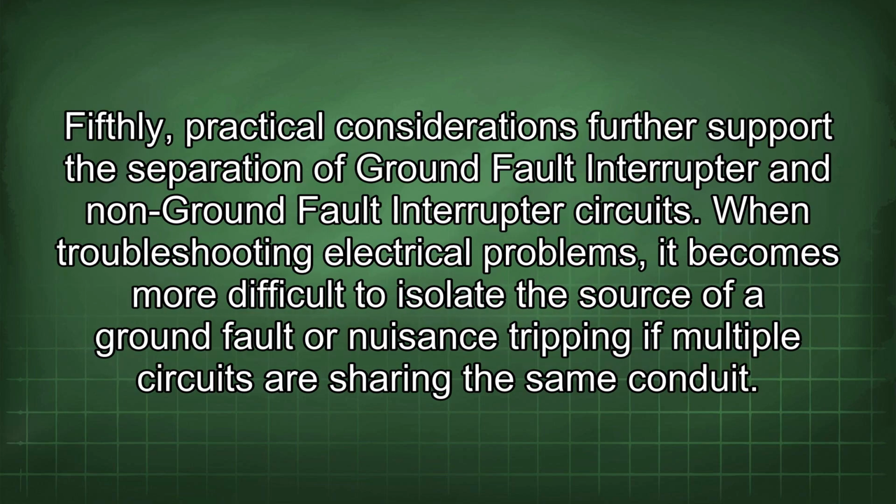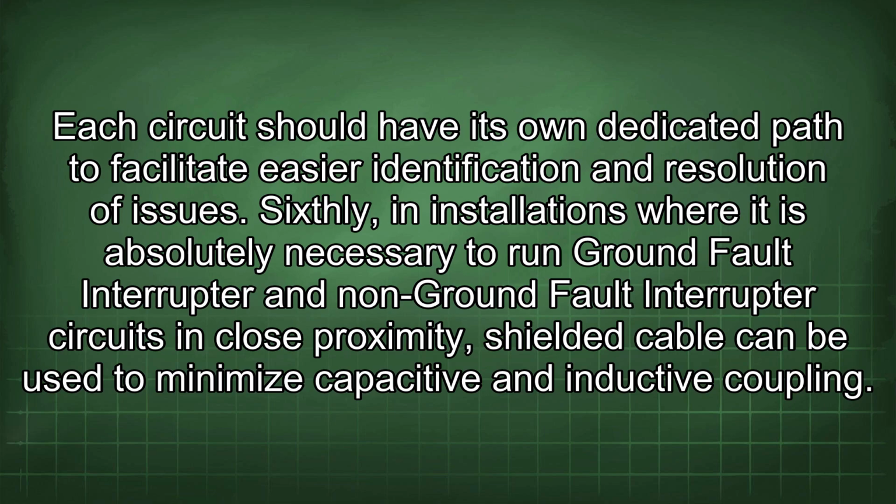Fifthly, practical considerations further support the separation of ground fault interrupter and non-ground fault interrupter circuits. When troubleshooting electrical problems, it becomes more difficult to isolate the source of a ground fault or nuisance tripping if multiple circuits are sharing the same conduit. Each circuit should have its own dedicated path to facilitate easier identification and resolution of issues.